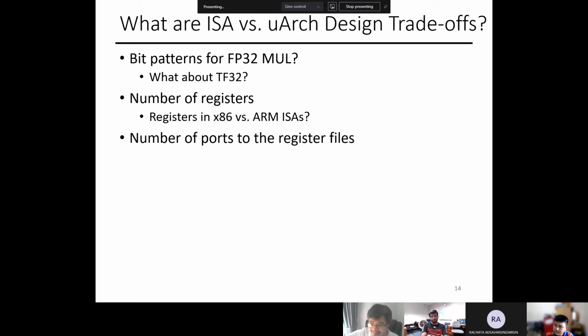So that's what a port does. If I have one port versus two ports, what's the difference? I can transfer data for one chip in parallel versus two chips in parallel, right? So the number of ports in the register files or in the hardware components do the exact same thing. It's how many of the same interface you're going to have on the hardware pieces so that you can do this data transfer in parallel.